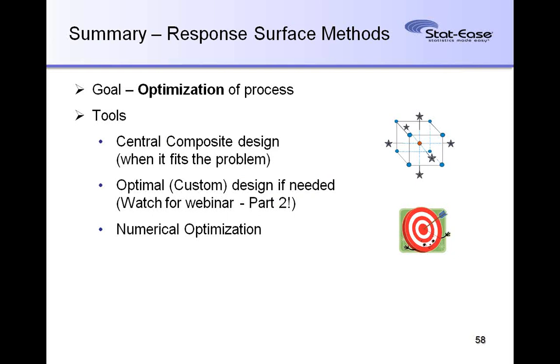Reevaluated would be the correct way of saying it, versus they screwed up. No, they didn't screw up. Remember, this design actually had 9 responses, and for some of the responses those ranges were appropriate, but for other responses it was just an overextension, and they went out a little bit too far. It goes back to that original slide that said if you need a higher order model, perhaps you need to reduce the design space, and I think that's what they hit in this particular case.